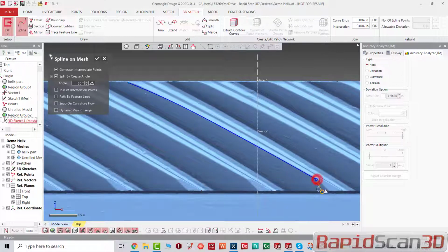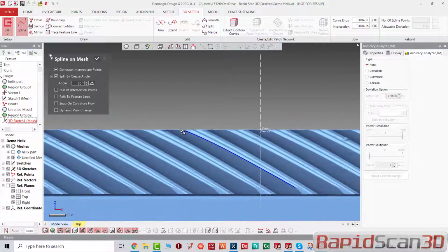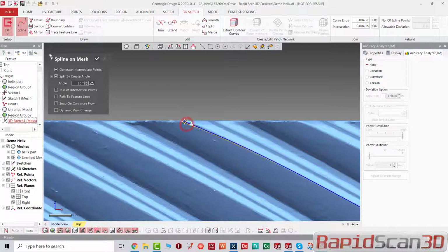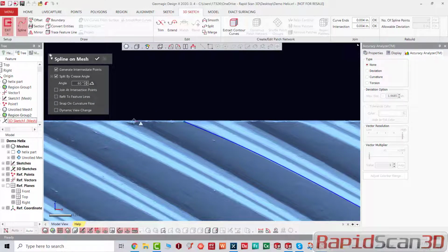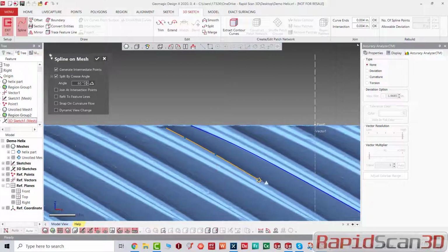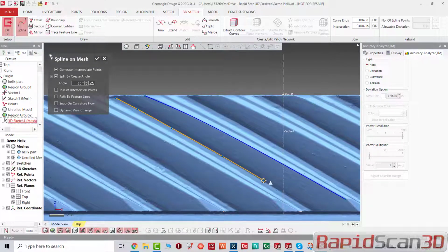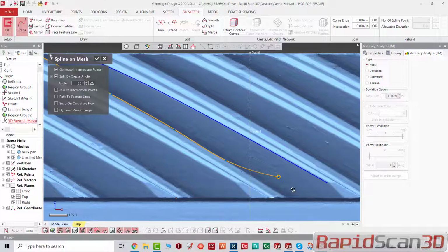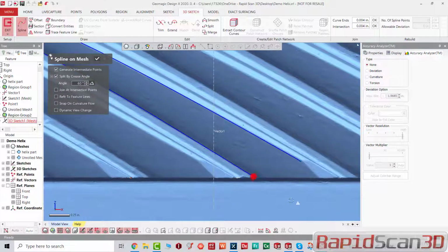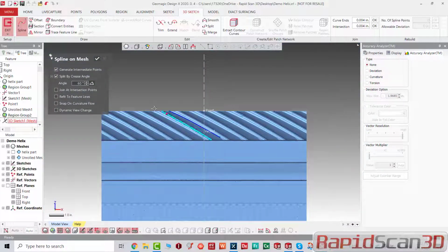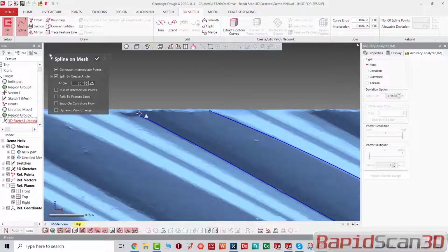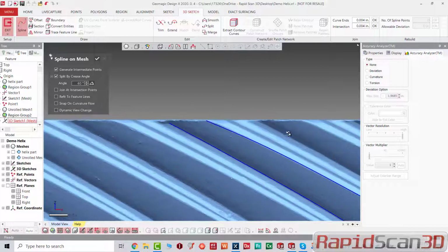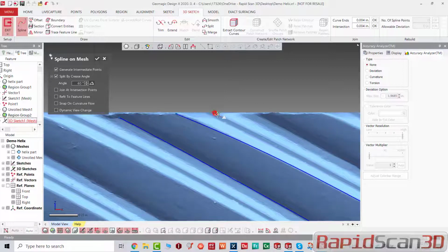So you can flatten it out, you can extract these 3D sketches, and we're going to go to the 3D sketch and then start creating splines. Spline on mesh is very powerful. I don't need any planes, nothing to attach to a mesh, so I can just start sketching in a normal view, and then I can start recreating my curvatures.